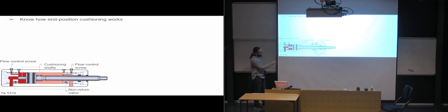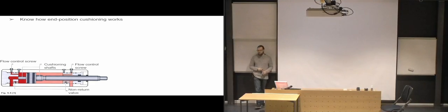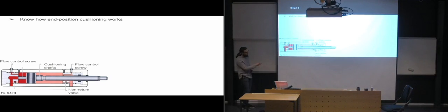The same happens on this side, only it's a little bit differently shaped because of having the entire piston rod going through there. The shape here is just having a slightly thicker section of the piston rod at the end, so that it's going to block off the opening between the piston rod and the guide as it reaches the end there.